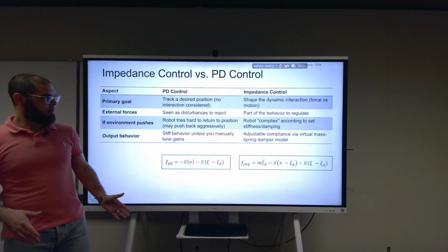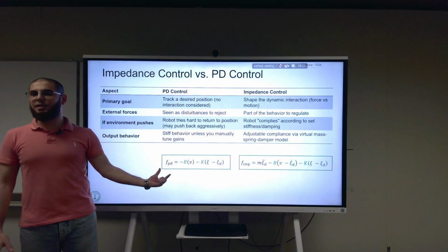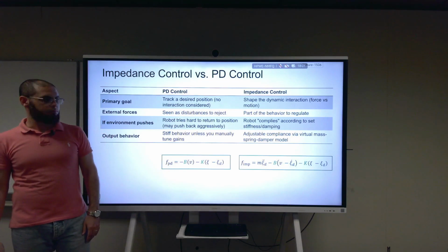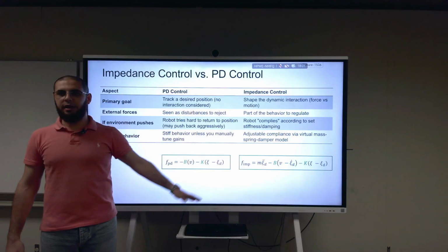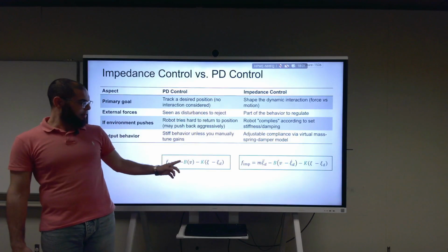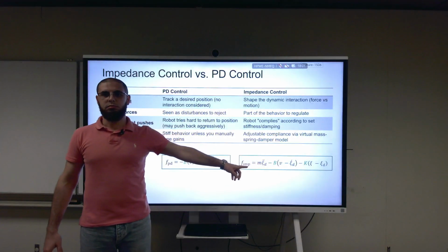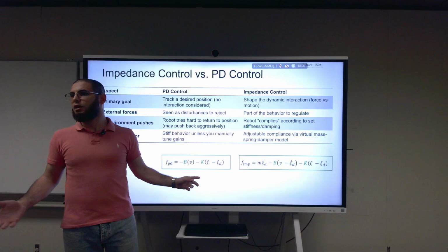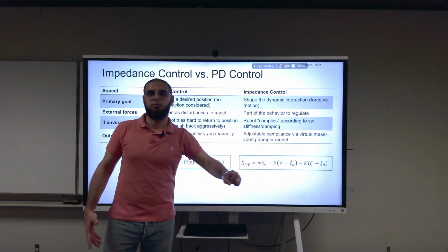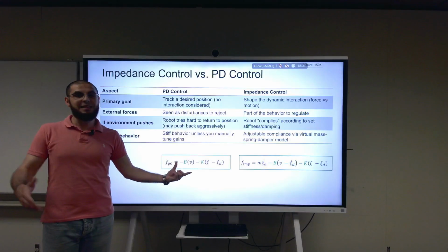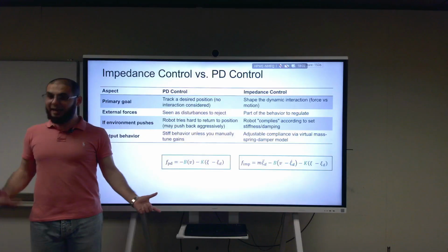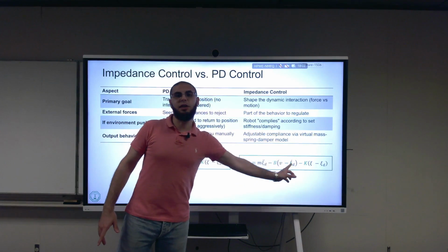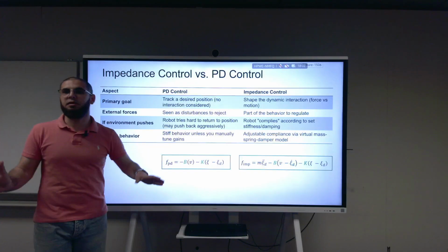Makes sense, right? Take a look at the two control laws. If we design the PD controller for F, what's the difference now? M psi double dot desired, and the negative psi dot. How can we make this controller into that controller? Simply by doing tracking. This was a stabilization controller, so PD was for stabilization. If I want to do tracking, I'll get the same control law. Yeah, so it will be PD, but a tracking PD controller. Tracking a trajectory, yeah. And psi desired, this will be the feed forward term, and this will be the velocity of the desired trajectory. So in the end, there is nothing there, right?